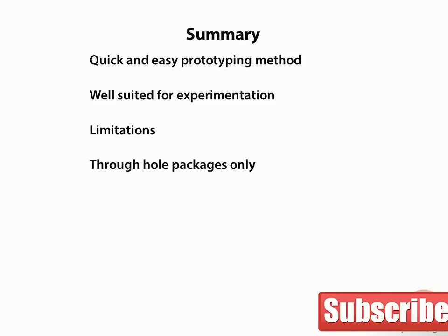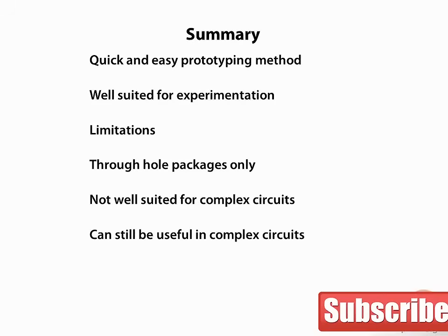There is some contact resistance on the spring contacts, and this can make a difference in some circuits. High-frequency circuits are not well suited to be prototyped by breadboards, and surface mount components are right out. Breadboards are not a permanent or hardy circuit solution. Breadboards, on the other hand, can be used in conjunction with other methods to build some very complex circuits. Later on, we'll cover some more complicated and permanent circuit building techniques.